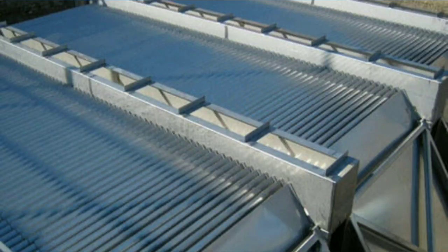Here the figure shows a typical plate settler, and these designs generally provide more equalized flow through the plate sections. The series of plates are arranged inclined at around 55 degrees to the horizontal, and a common flow collection pipe or channel is provided commonly to two of the channels. Because of these arrangements, the cleaning operation and maintenance inspection are very easy when we compare this with the typical sedimentation tank.